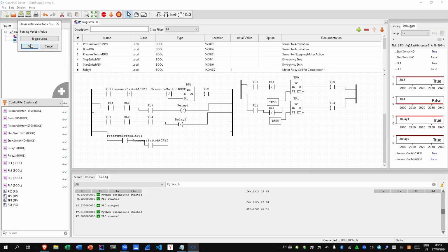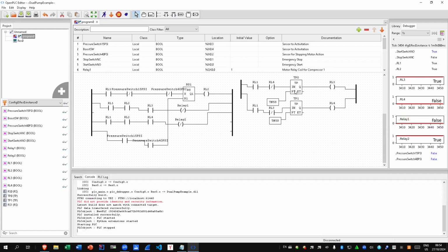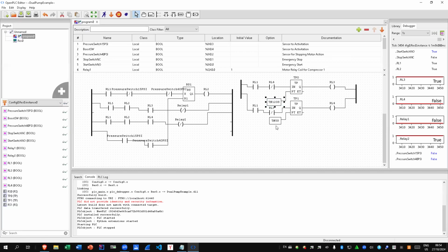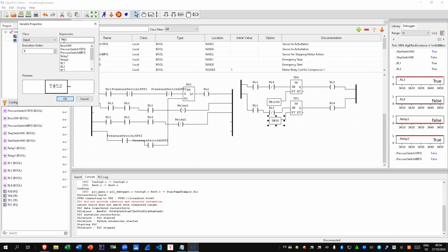But once this goes down, we now see one of the pumps actually turn on. So they're just circulating between each of them. So if we set this one to something like 120 seconds or 2 minutes, we will just have a constant input to the system.